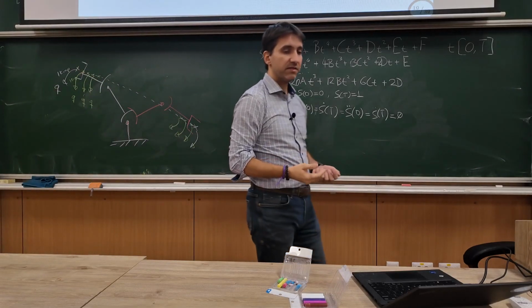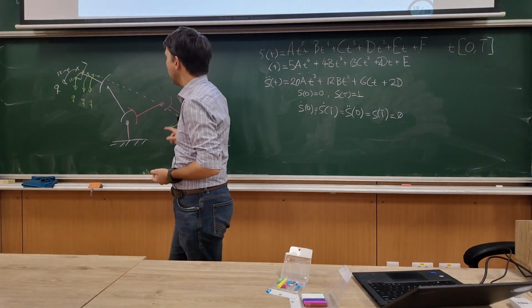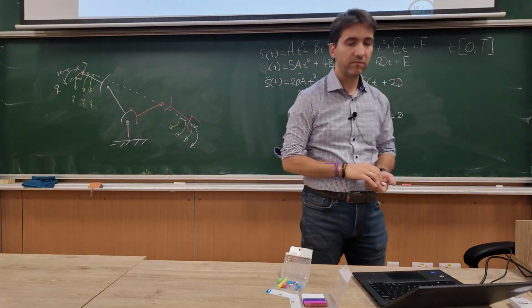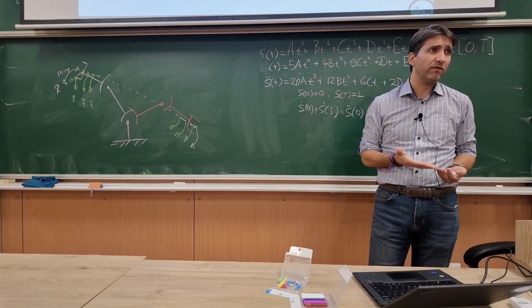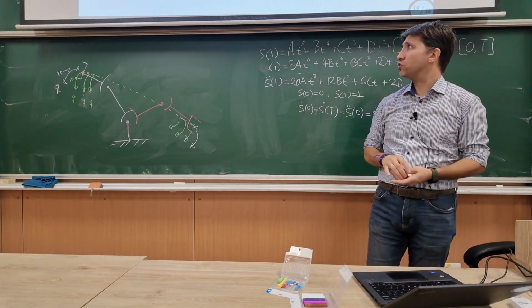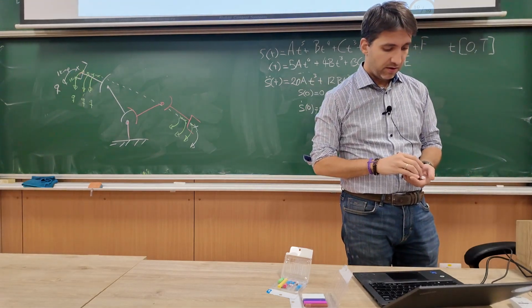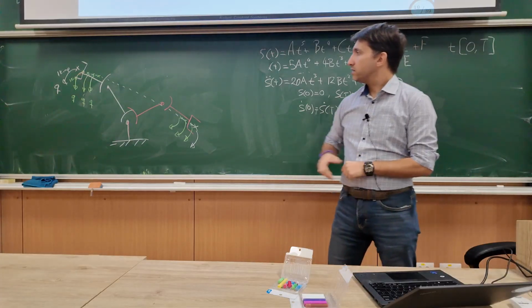And basically I will convert this line trajectory into joint trajectories by solving the inverse kinematics there. Because I need to go to joint trajectories, because that's what I'm controlling. In the end, I can only move the joints, so I cannot stay in the end effector trajectory.